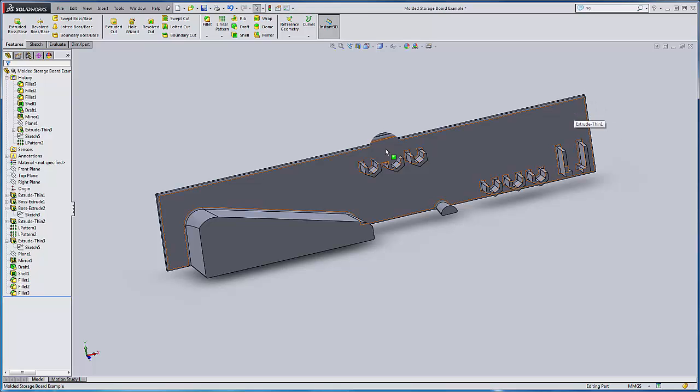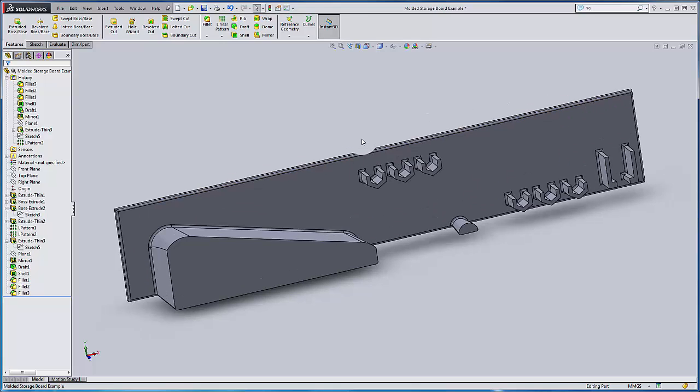Notice that if you introduce holes here, those can't actually be injection molded into the simple right and left half cavities. So you'd have to do something a little bit more creative than simply put a hole in. So I'll leave that to your devices.